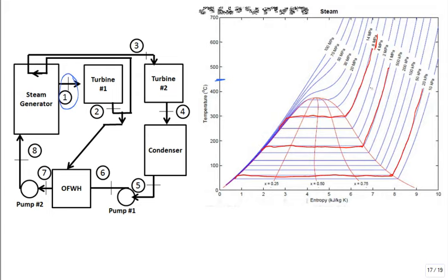Isn't it right there? I expand it isentropically. Maybe it lands right there for state 2. I then reheat, maybe I reheat back to 440. That's state 3. Then, what do I do? Maybe I should color code this differently. Is that blue hard to see? It's fine? Okay. I just switched it to black. All right. Now we push it through the second turbine from 3 to 4. There's state 4. True? Did I do that correctly?